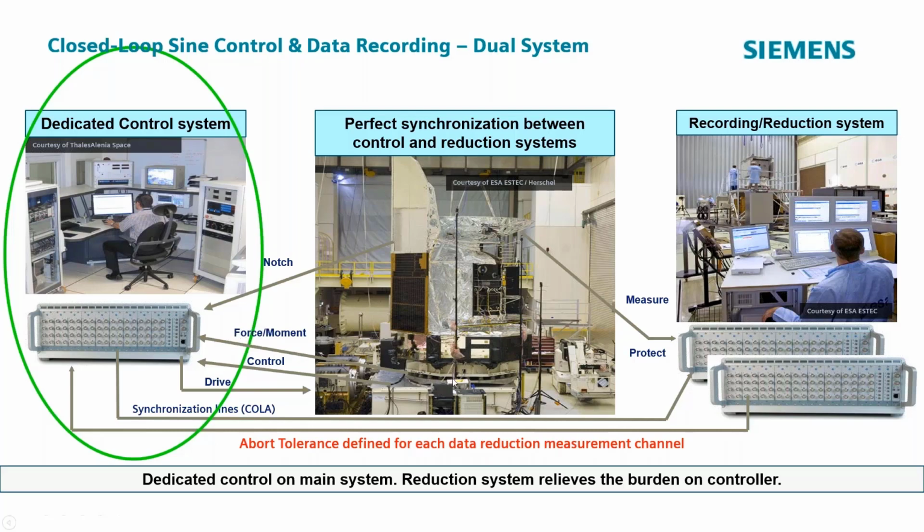And you limit the force input because of mechanical impedance mismatches between a shaker situation, which is typically much more rigid than what you have in the field. So the input can over vibrate your structure or over test it. So force limiting is a way to take care of that. That's a whole other seminar to talk about.